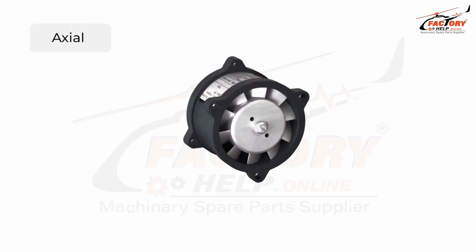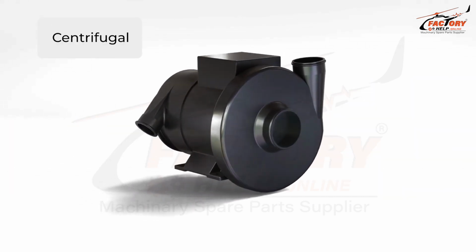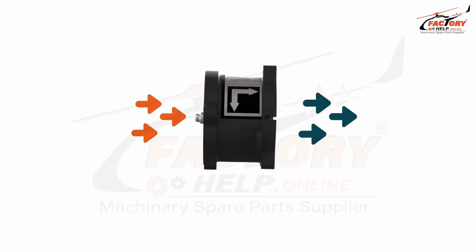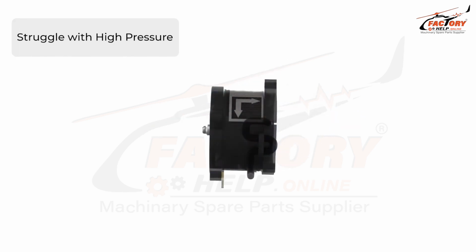An axial fan is a highly efficient, lightweight way of generating a high airflow in an axial direction. The flow of air enters and exits the fan axially. Still, it can struggle with high pressures from restrictions caused by fixed or variable airflow resistance. It is, therefore, critical when selecting an axial fan to understand the airflow restrictions and not operate the fan at a point that will cause it to stall.